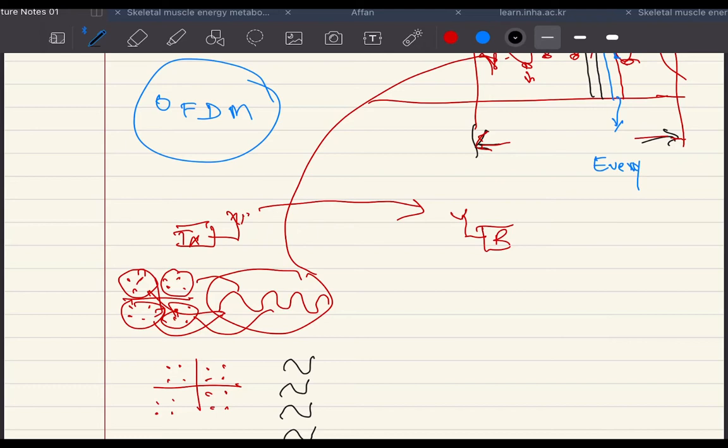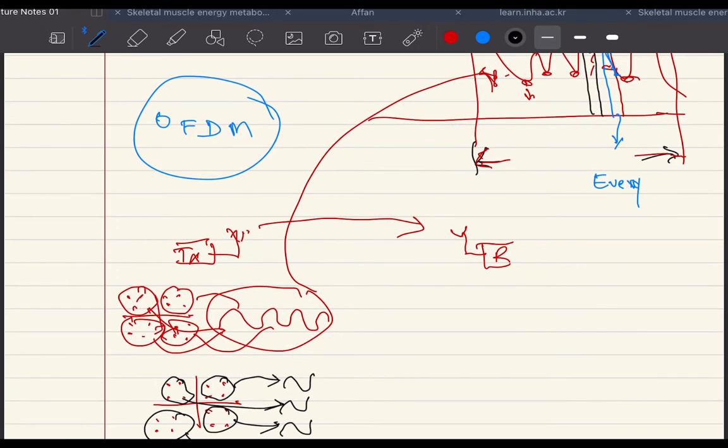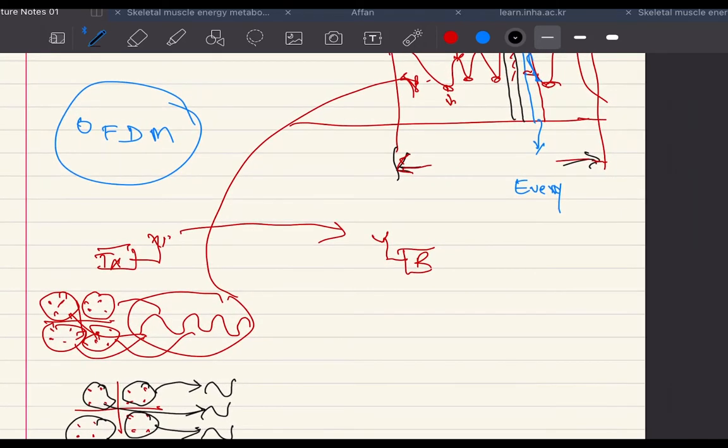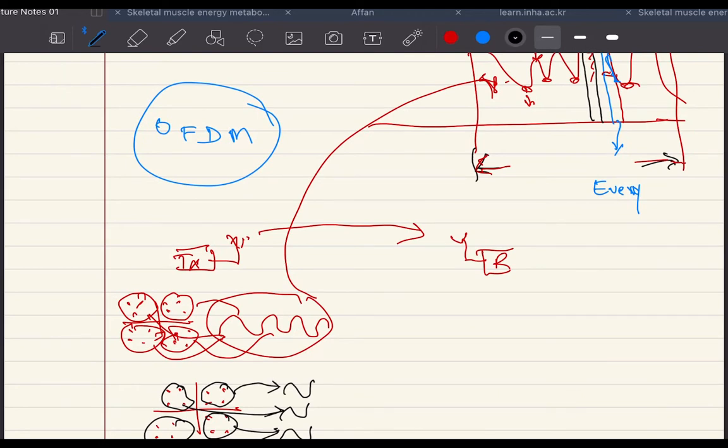So you are partially transmitting the data on this subcarrier, then another data on this subcarrier, the other data on this subcarrier, and the other data on this subcarrier. Although you are doing the same thing, you are using multiple subcarriers. In other words, you had this much of bandwidth, so you sliced your bandwidth, and then you are using it for different subcarriers, for different types of data.